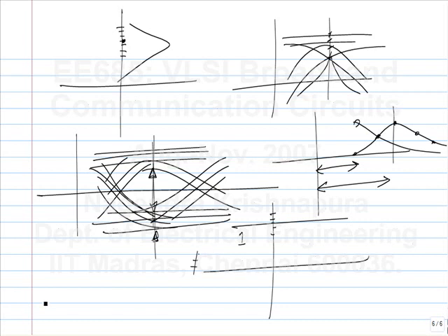You have post-cursor ISI, so you try to subtract off this one. That's why you need the negative post-cursor tap in the equalizer. That's the idea. How much exactly you make the tap depends on different measures of error. The first thing may be, I'll reduce this completely, I'll make it 0. Then you see that you have some residual term left out afterwards. So maybe you try to minimize the composite effect of the 2 taps. That's what you try to do by minimizing the sum of squares around this 1.